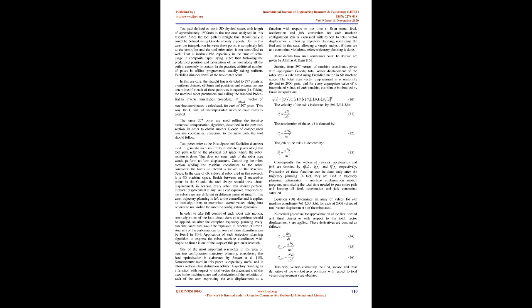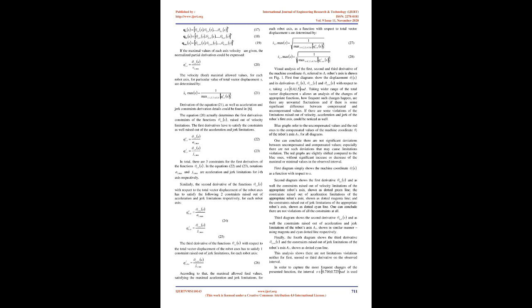Next, the differences are calculated for every i equals 1, 2, 3, 4, 5, 6. These 6 vectors with length 6 are organized as a 6x6 matrix, and that matrix divided by the iterative step is actually the Jacobian matrix J. The machine coordinates are then corrected by the Jacobian inverse multiplied by the vector fx.